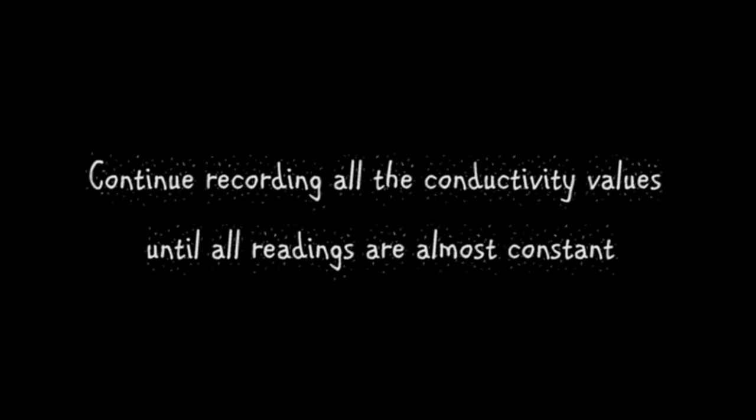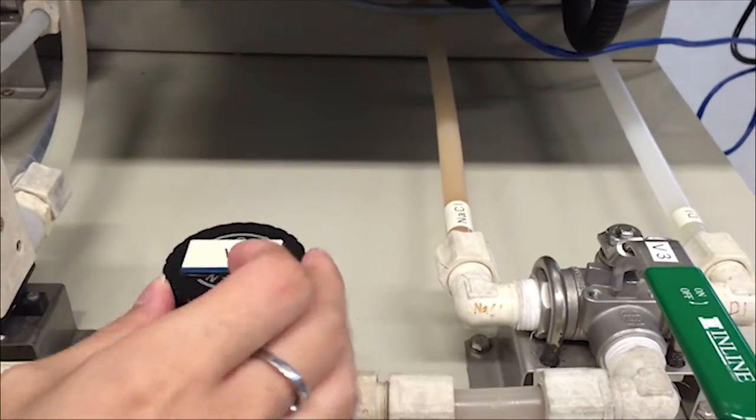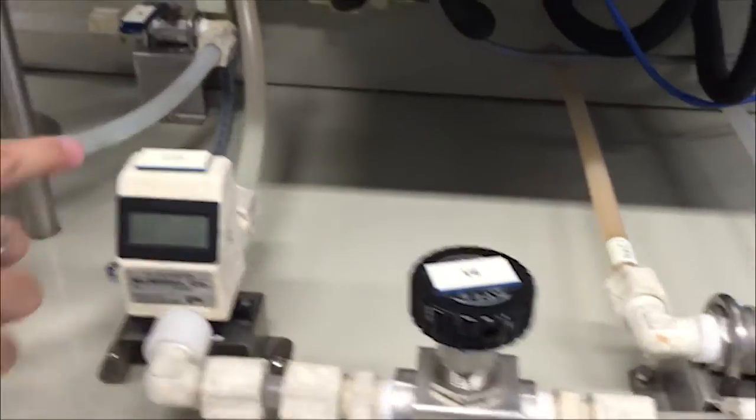Conductivity values of CT1, CT2 and CT3 are recorded at suitable intervals. Continue recording all the conductivity values until all readings are almost constant. Lastly, we switch off pump P2 and close valve V4.